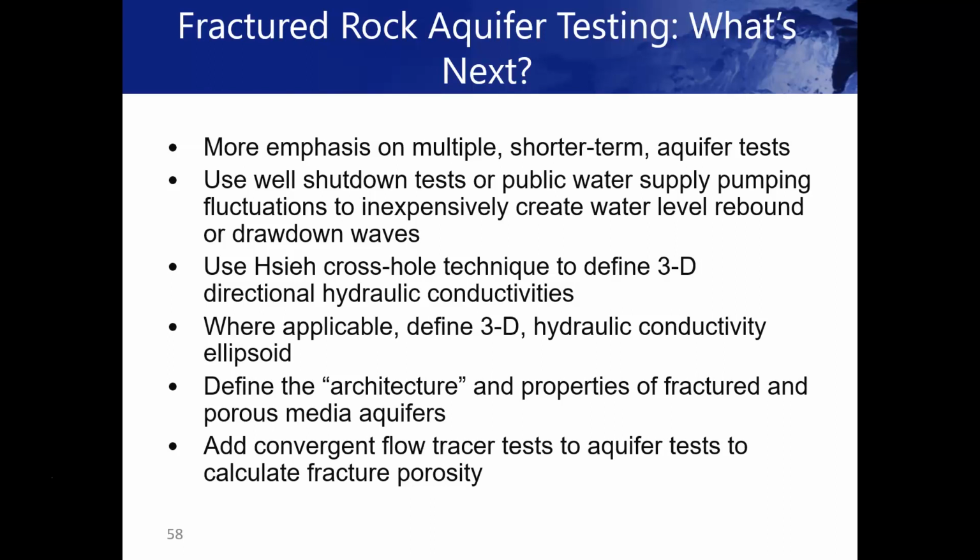Yeah, that's a good point. There are some aquifers that may have boundaries. And in fact, the one I mentioned, the Buried Valley up in New York State, is a very laterally defined channel filled with gravel and sand. It's cut and eroded into a moderate to low permeability rock, which forms a boundary on either side. And in some of the aquifer tests that have been done there, we've seen the rebound. I mean, I'm sorry, the boundary effects of the drawdown, in a sense, bouncing off the rock walls and rebounding back into the aquifer test area.